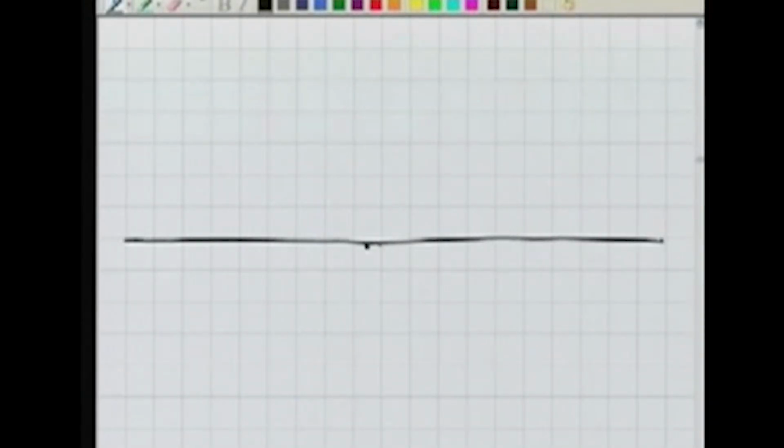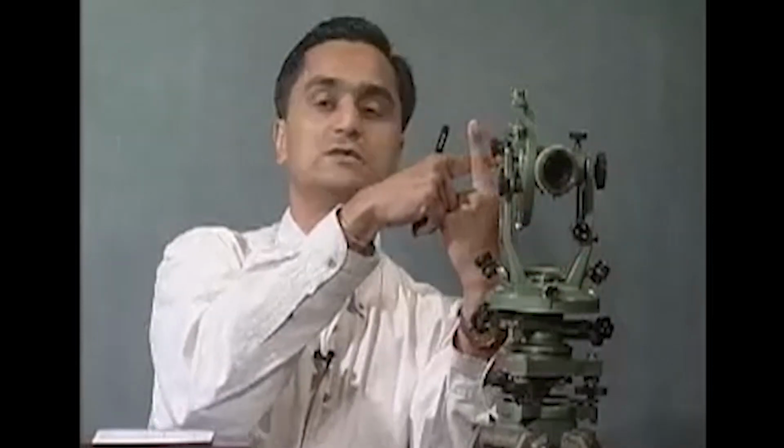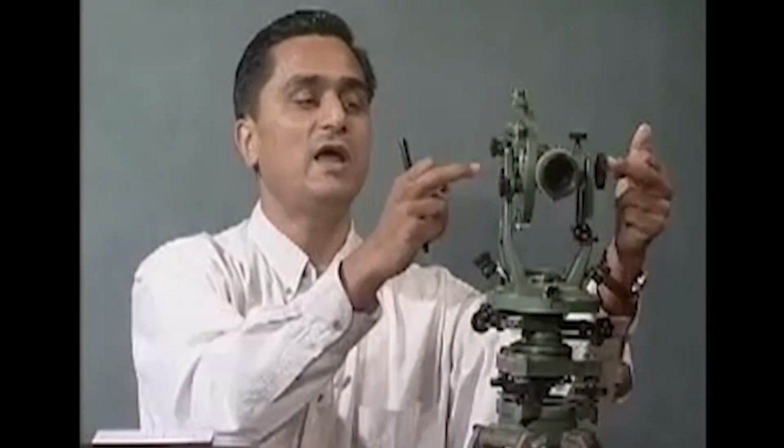Our point O is somewhere here where the observer is. We have our ranging rod A and our theodolite is kept here. Now the problem is, okay, for me, the face is towards my right, the cross wire is shifted. Now if it is so, if I rotate it, it is making a plane. So basically what is happening here, if you see, the cross wire is shifted. The line of sight now is making an angle with the horizontal axis which is not 90 degrees.